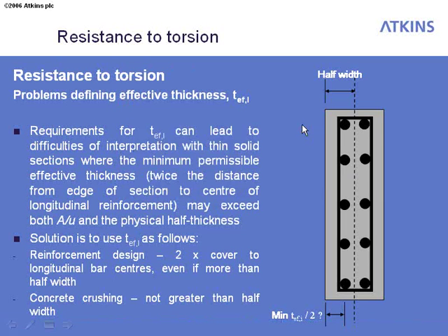What you could do is come back to where we started with the compatibility torsion and select the torsional stiffnesses of your M-beams to be very small, such that the torsions are indeed very small. That was the way that most of our European friends envisage you do these decks, and not the way that we do them, by putting the torsional stiffness in and then trying to design for that torsion. So that's what arises. But given that a problem exists and you're trying to design something like this for a torsion, what do you do?